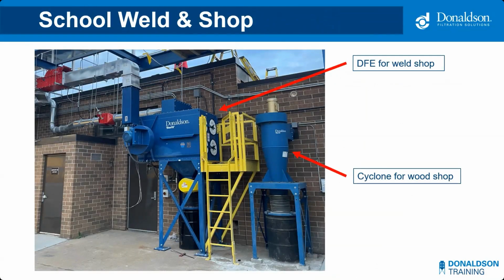Here's an example of how I use the DFE collector for a weld fume shop, and a Cyclone collector for a wood shop. As you can see there, sitting side by side. Basically, this was another high school in Wisconsin, Seymour, which you may know of. They love the operation of the two systems because they have the Cyclone with a spark cooler in it, so we can minimize any sparks or any fires in there. And basically on the cartridge collector, they can actually put mitigation equipment, as you can see on there, those red devices there, and protect the operators and people and students inside the building for a combustible dust issue.